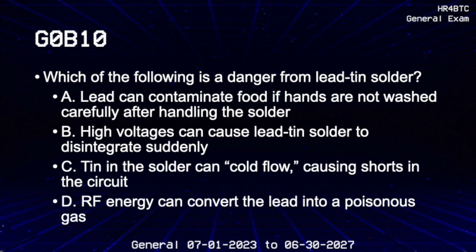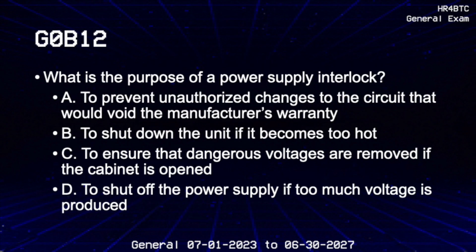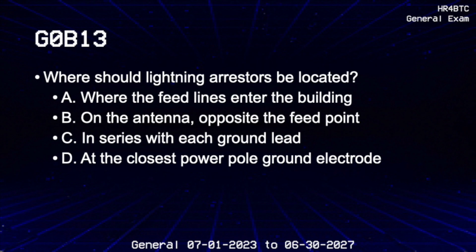Which of the following is a danger from lead tin solder? Lead can contaminate food if hands are not washed carefully after handling the solder. Which of the following is required for lightning protection ground rods? They must be bonded together with all other grounds. What is the purpose of a power supply interlock? To ensure that dangerous voltages are removed if the cabinet is opened. Where should lightning arresters be located? Where the feed lines enter the building.